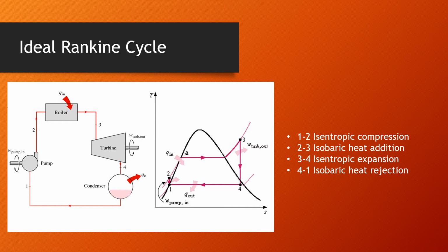You'd add heat into the boiler, make steam, and use that steam to rotate a turbine and generate electricity, and the exhaust from the turbine or steam from the turbine would be fed through a condenser to condense it back to its liquid form, and then water would be pumped in again to feed to the boiler and keep on going with the cycle.